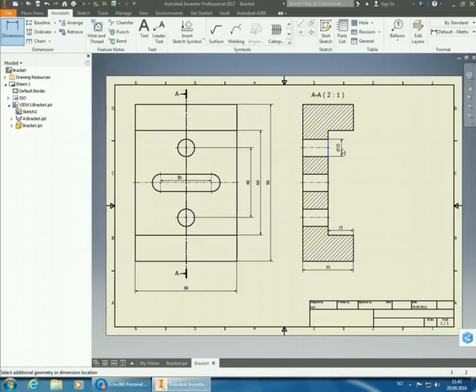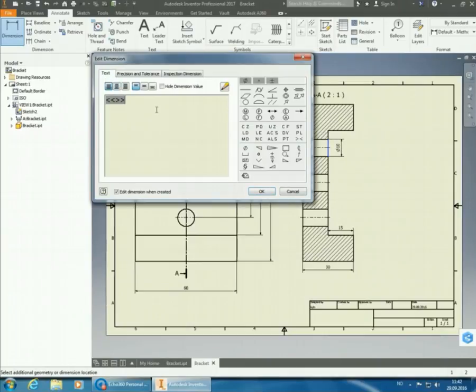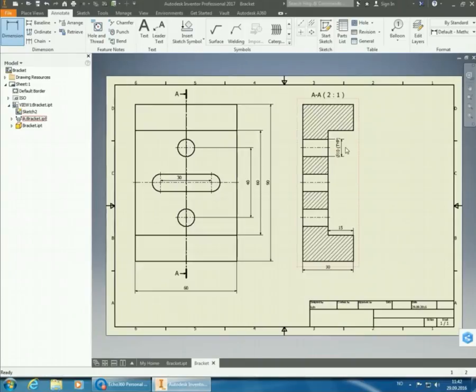So I'll put this one in here, and I'm going to add tip to it. There was no room for a tip inside there, so I just need to move it outside so that I don't have these broken dimension lines on it. And since this diameter of 10 is typical, it means that it is typical for this hole, for that hole, and it's also typical for the ends of the slot, which means that the width of the slot has to be 10 also.